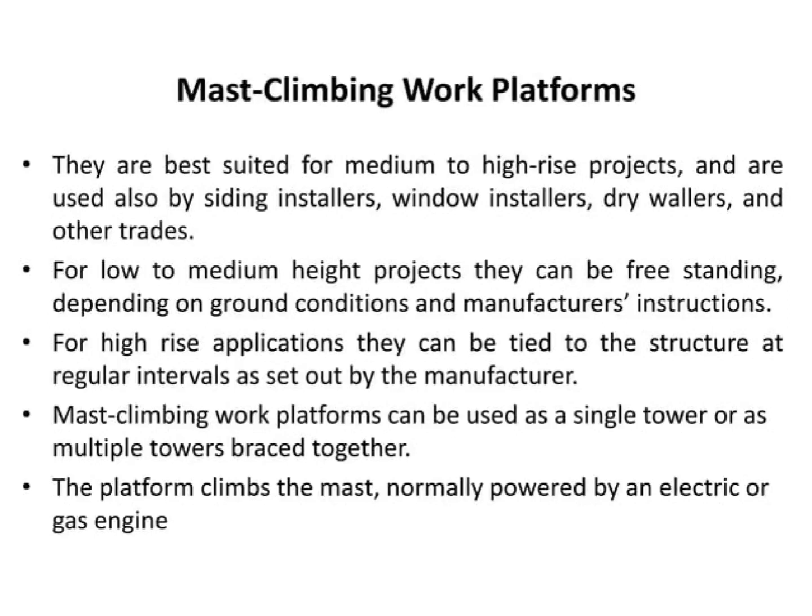Mast climbing work platforms are suitable for medium to high-rise projects due to their stability and fast access for drywallers, window installers, siding installers, and other trades. For low to medium height projects, these platforms come as freestanding, but for higher projects, they require ties to the structure at defined intervals as instructed.